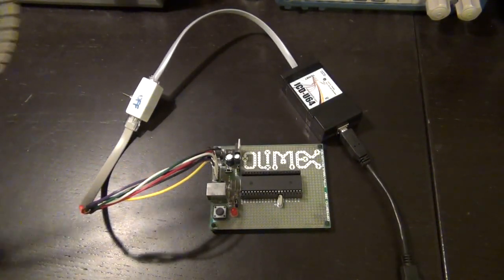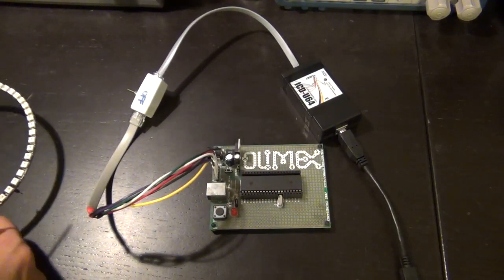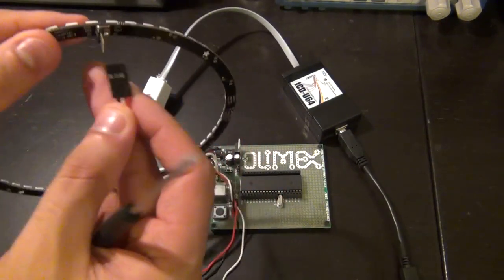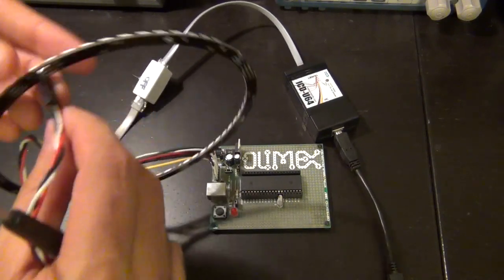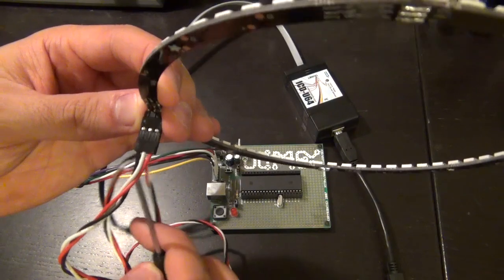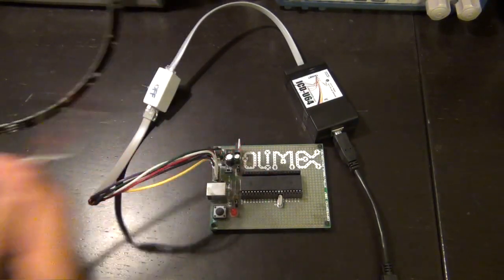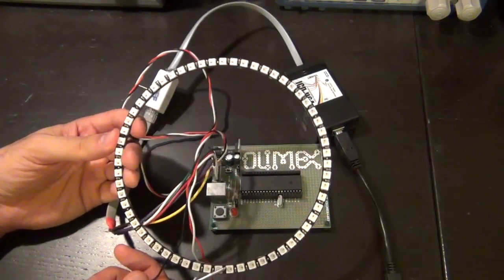And what we're going to do is connect this guy directly onto here. I have a little cable here that I have made. It's very straightforward. The cable just plugs directly into here and is color coded like so. And there it is. The red is VDD, white is the data in, and black is ground. Then I have these three guys at the end which I can plug directly into the evaluation board. And that's it. That's all you need to program this little guy.